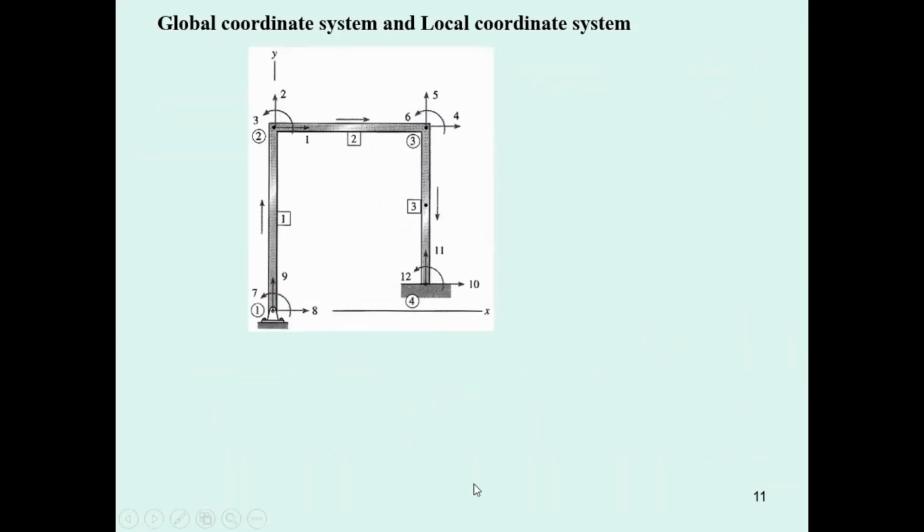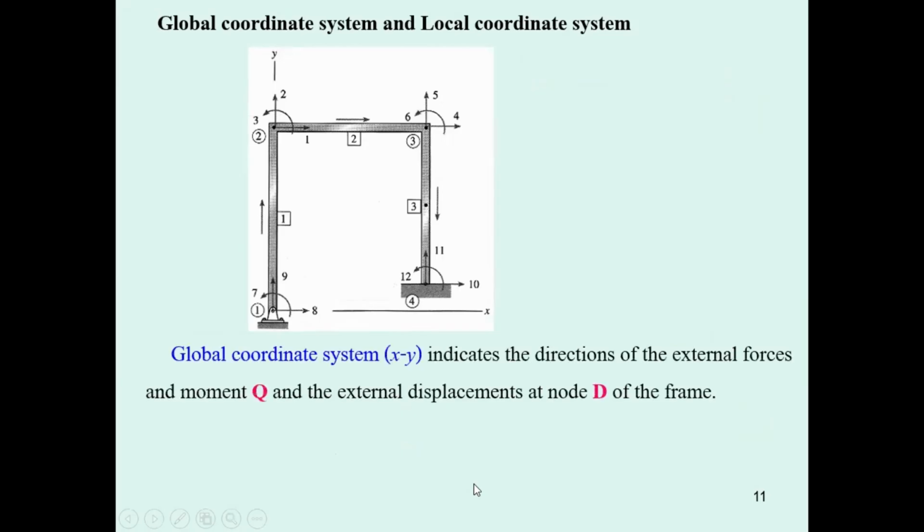Okay, let us again review the global coordinate system that's going to relate the capital Q matrix with the capital D matrix. Most of the calculation for the beam and the frame doesn't require much about the coordinates, because as Ajahn mentioned, you have to know about lambda sub x and lambda sub y if you recognize this kind of local coordinate.